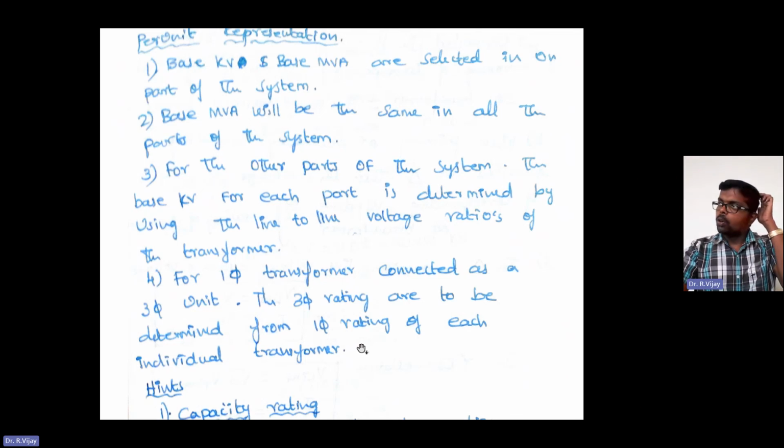Sometimes, while doing a simulation, instead of going for a three-phase transformer or three-phase generator, we'll use three single-phase generators. Same like that, the three-phase rating is to be determined from the single-phase rating of each individual transformer. So these points also you need to remember.